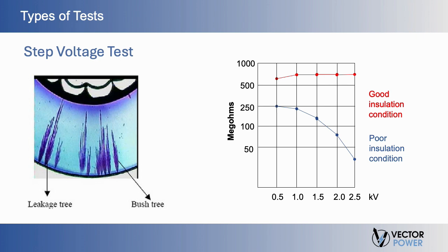However, it must be remembered that an overvoltage test can lead to a catastrophic failure if the insulation breaks down because high voltage test sets, such as high potentials or high pots, have a lot of power available. An undervoltage test carried out by an insulation resistance tester has relatively little power available and is far less likely to result in a destructive test.